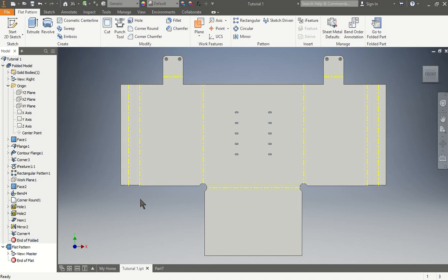Once that's done, we're going to set the order of the bend. So we're going to go to bend order annotation. See how it's adjusting? It already tells us, it's saying first you bend number 1, then you bend number 2, then you bend number 3, 4, 5, 6, 7, 8, 9. If that number is okay, we could keep it. But in our case here, is it good? 1 is good, 3, 4, everything looks good. 7, 8, 9, 10. You could change the order if you want.